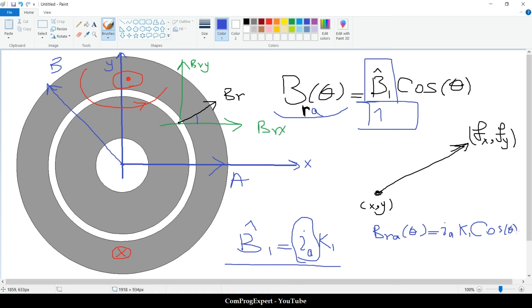You know that. So I want to use these variables and use time functions. We know that for a three-phase induction motor during the steady state operation, the values of the currents are not equal at any instance of the time. We know that if we use a star connection, the summation of the currents is zero.